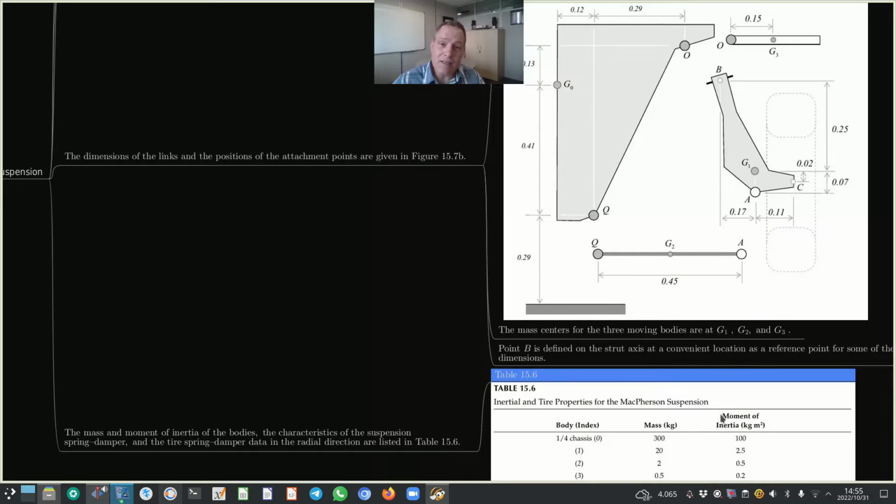But if it is important for you to have very good accuracy and very accurate time response, then it is a better practice to include all the bodies with their mass properties, being weight and moment of inertia, and then wait a little longer for the simulation to run.